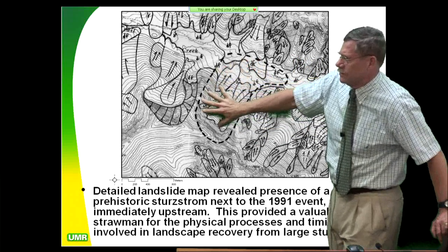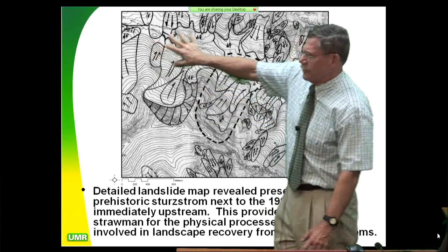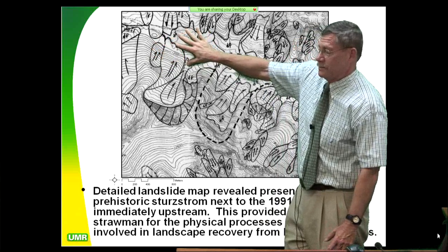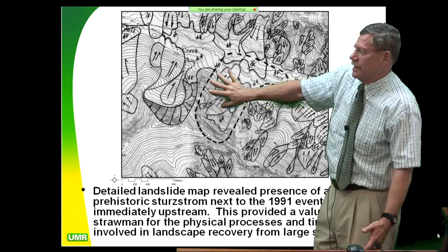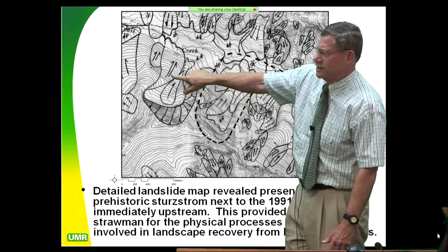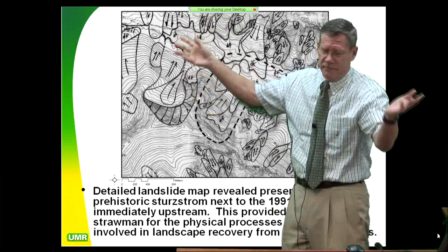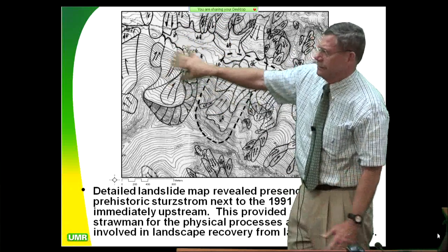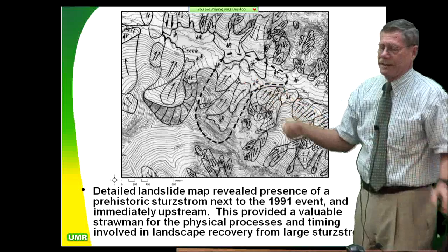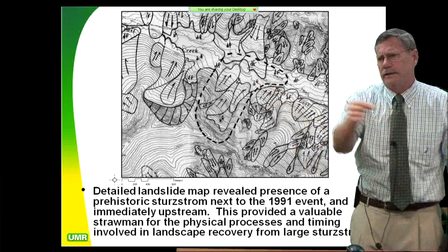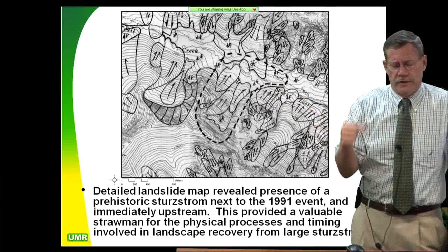And of course, you have to take into account what the stream power effects are in the analog and the precipitation versus the one you're studying. Now, in my case, it doesn't get any better than to have your analog right next door, because that takes away a lot of the variables. Same geology, same watershed area, same creek, etc. And you don't get that lucky very often. But generally, you're going to look in the immediate area for other analogs.